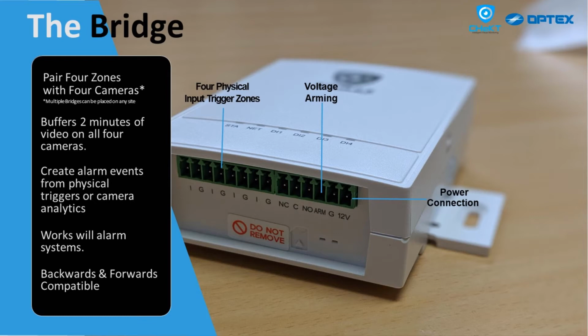If you needed more than 4 cameras to push to the monitoring center, you can add additional units to a site. And so we'll go over a few sites and I'll show you how that works. The appliance can work with any alarm system because of the way we supervise the zones, the physical zones or wireless zones, and the way we receive the arming information of an alarm panel. You'll see there's a voltage arming pin on the bridge. All alarm systems have a voltage output that you can program to change states based upon the arming and disarming of that alarm system, and so we can just supervise that voltage.